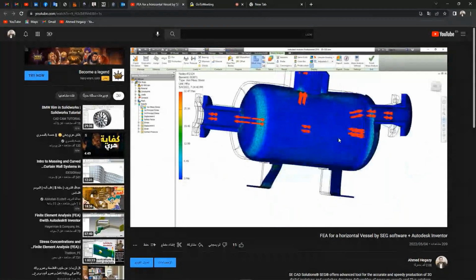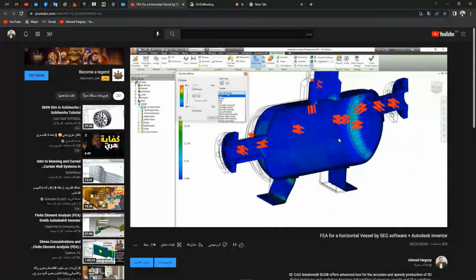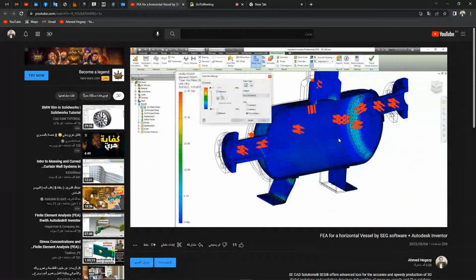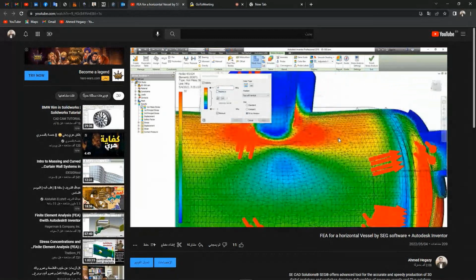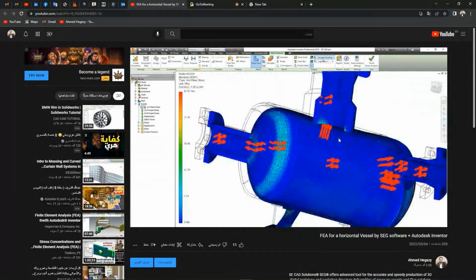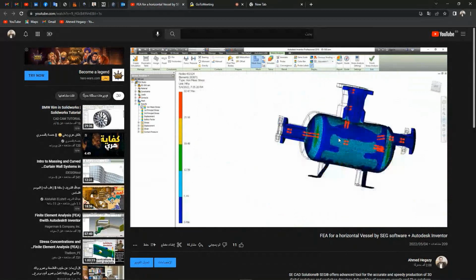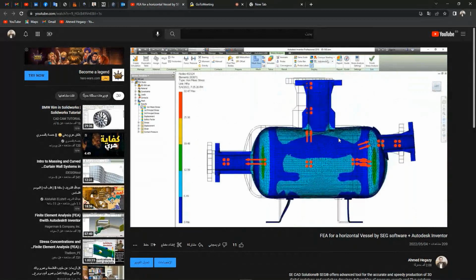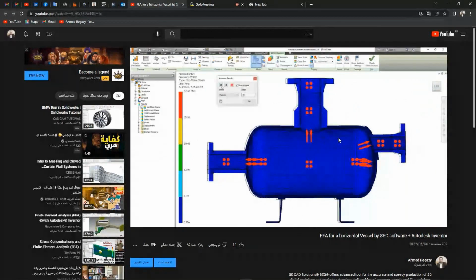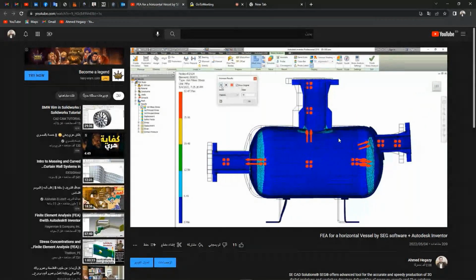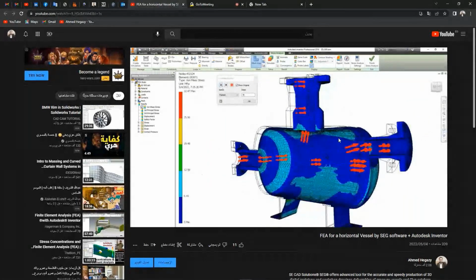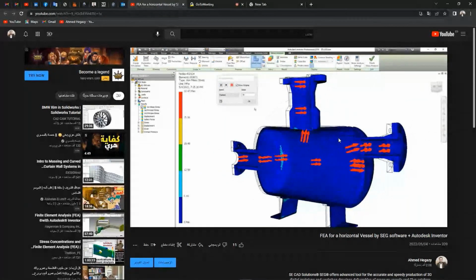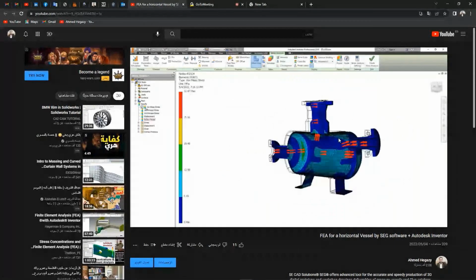But you still need to make one more step, which is the stress categorization, because finite element analysis software like ANSYS or Abaqus or any other don't do the stress categorization. So you will need to sum the primary stress plus 1.5 times the secondary stress. All of those categories you will need to recalculate manually. I hope the point is clear now.